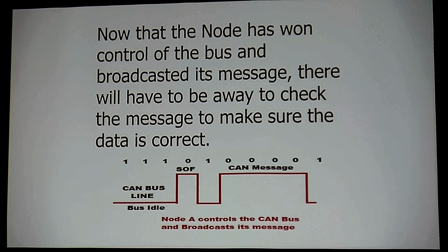So I make one point here for the MAF, I make one down here for the O2, another one for the TPS, another one for the APPS. Then I finally get back to the MAF to make my second point. Do you start to see that this is a circle? It's a loop that I'm requesting. The more PIDs you have in there, the lower their latency is going to be. So this is a problem for us. You just got to understand how it works, and you'll be ahead with these systems.